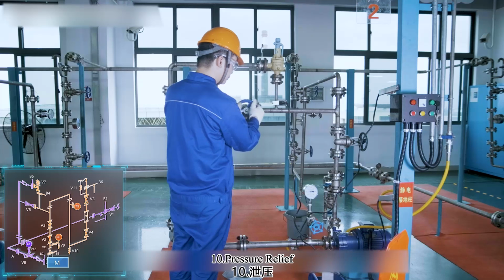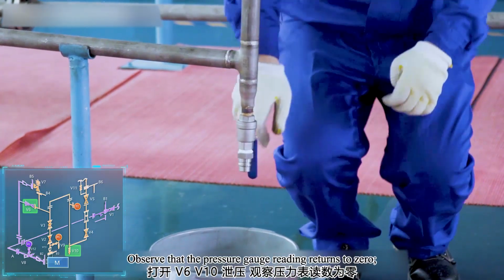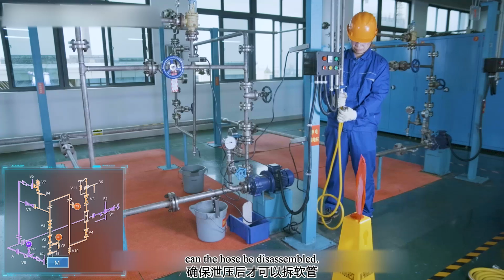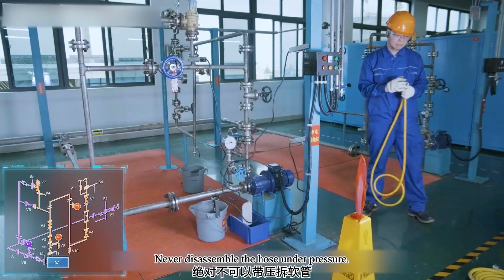Tenth, pressure relief. Open V6 and V10 for pressure relief. Observe that the pressure gauge reading returns to 0. Only after ensuring complete pressure relief can the hose be disassembled. Never disassemble the hose under pressure.